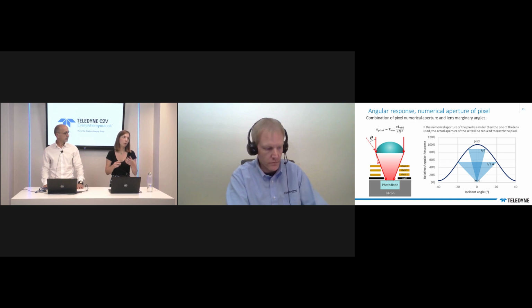And yes, one of the challenges can be the pixel size decrease. It's a challenge for the image sensor manufacturer, and also for the lens makers, to have lenses compatible with and optimized for smaller pixel pitch. So sometimes it's finding a lens that can match a small pixel pitch. It's getting more common, but it's a permanent race. It can be challenging sometimes if you already have tough criteria for your lens.